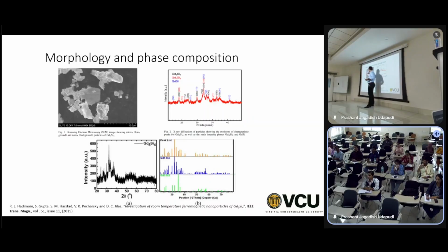Okay, and also the contrast of this will be different from the contrast of the other. In this case, it looks like they're similar contrast, and we have also done the EBSD, so it gives you a table of atomic percent. So we know that these are all gadolinium 5 silicon 4 particles. Okay, so you can do elemental analysis, and you can do morphology. You can see whether all are single phase or multi-phase. So that's what we have done here.